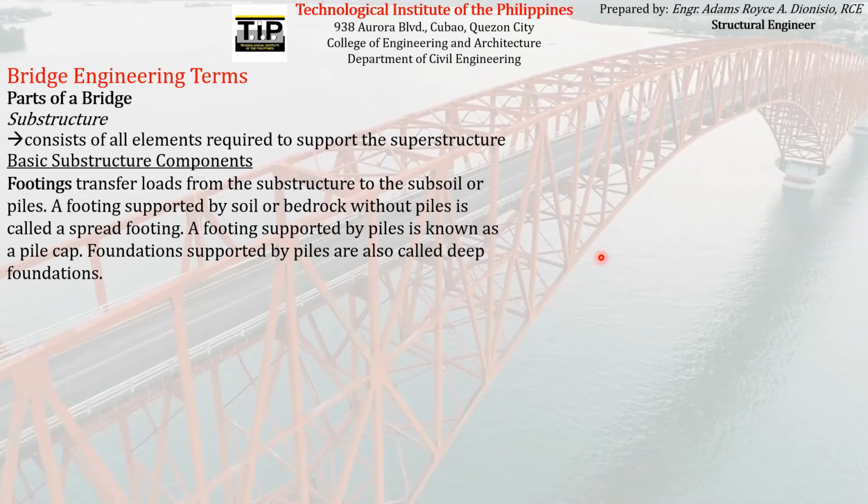Another component of a substructure, which is actually a major part of the substructure, is what we call the footing or footings. Footings transfer loads from the substructure to the subsoil or piles. A footing supported by soil or bedrock without piles is called a spread footing.